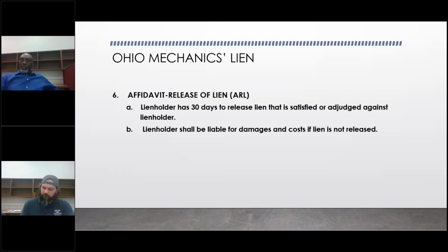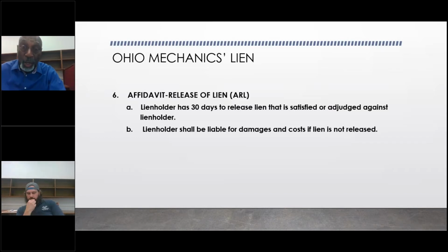Well, yeah, you're providing a service. Again, if all of the requirements for the lien have been fulfilled, and you file what you need to file with the county of the furnishings of what you provided, then you do have a recourse. Now, one of the advantages of taking advantage of the Ohio mechanics lien is that it might not be as cumbersome or time consuming as your common law remedies. If you perform a service and you're not paid for it, and you've got a contract for that, then you can always go to the Court of Common Pleas with a complaint against that owner.